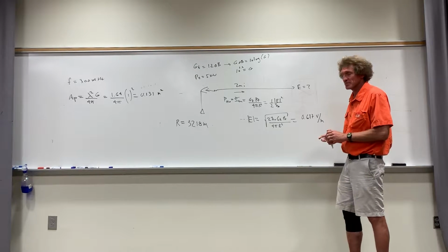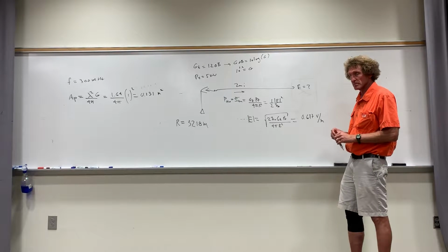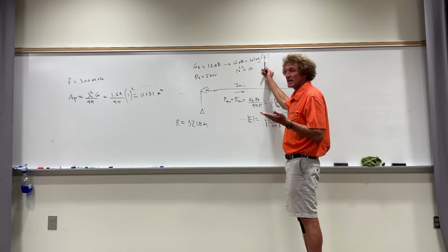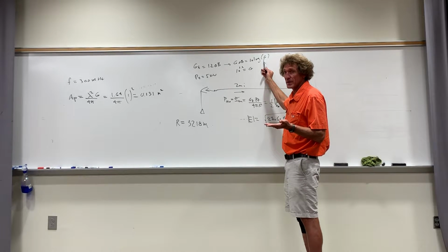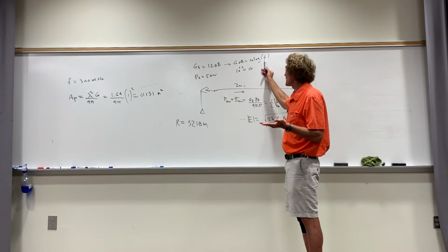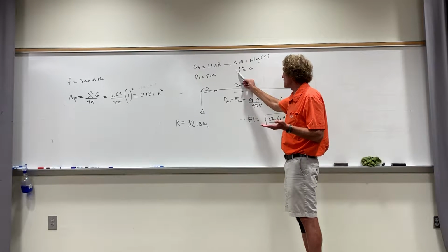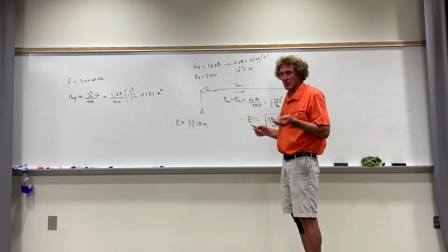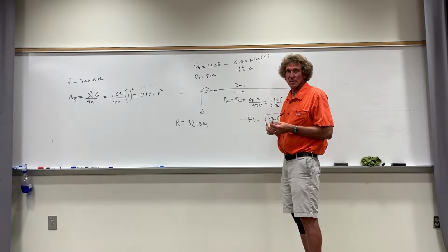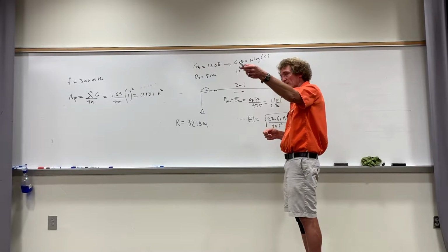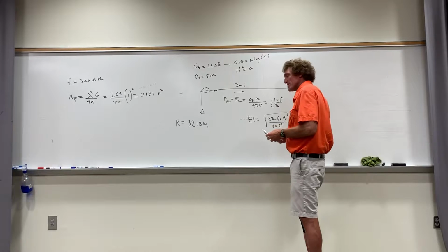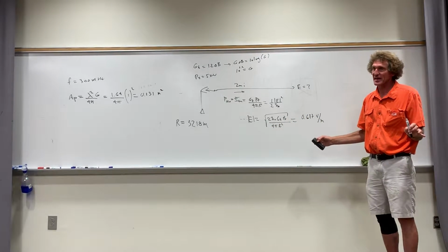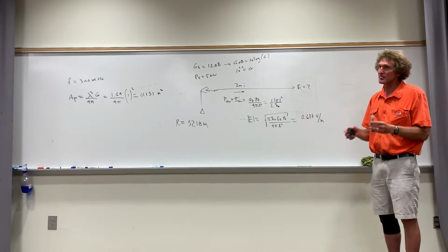I gave you a bunch. What is that value for the gain? Well, the gain in dB is 10 times the log of the gain in linear terms. Right. So now we need the linear gain for our equation. The way to get this is divide the gain in dB by 10, that's 1.2, and then take 10 to that power on both sides. Do y'all follow me? Can you see in the back? Okay, and over there in the far back, it's important you see this. You can't get casual about this. This is the kind of stuff where people make all sorts of odd mistakes.